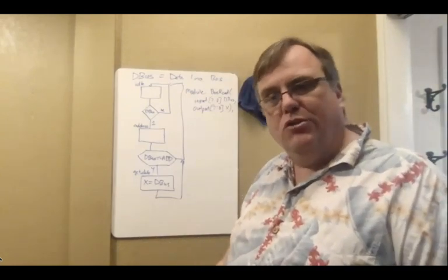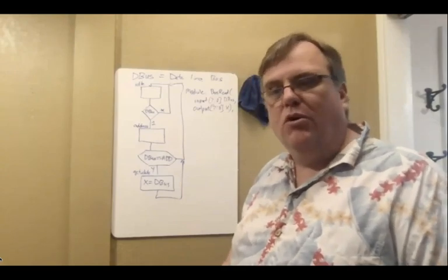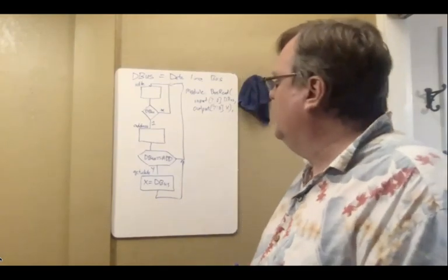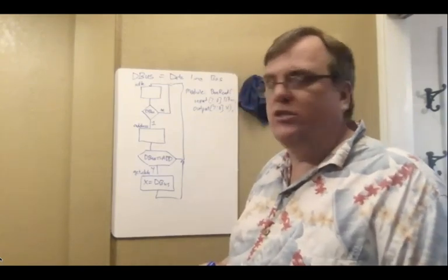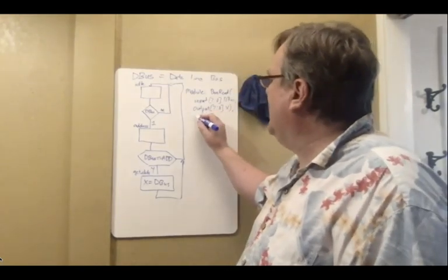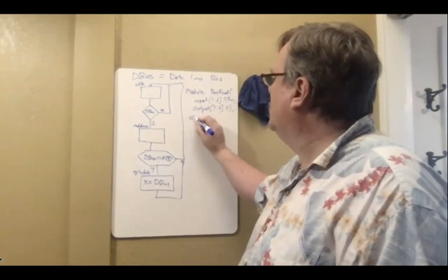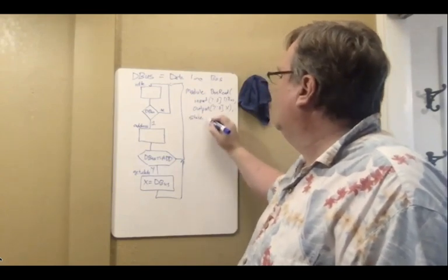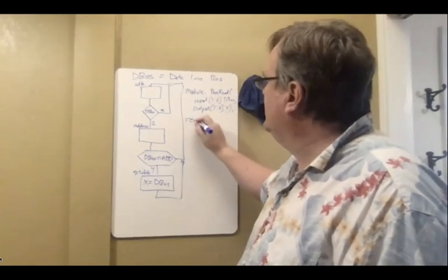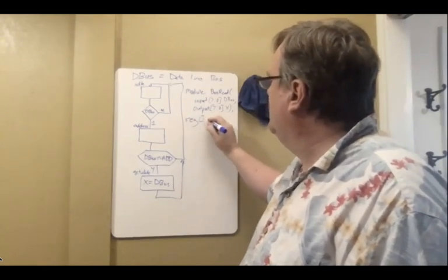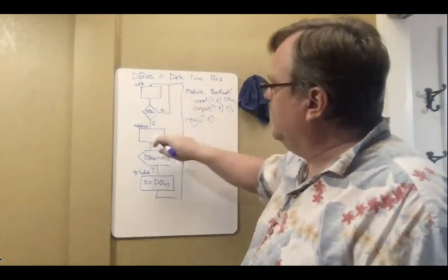So if I'm concerned at keeping things as small as possible, and I am worried about error stuff, I might decide to pick gray code as my transition. So that means my state, I need to say what it is. It's a reg 1 to 0 because I need 2 bits for gray code to have 3 different things.